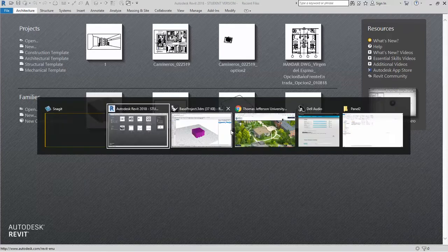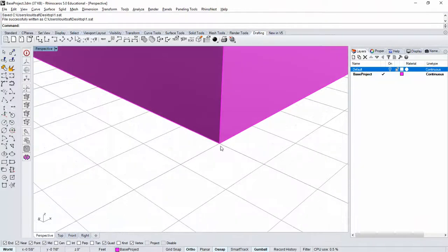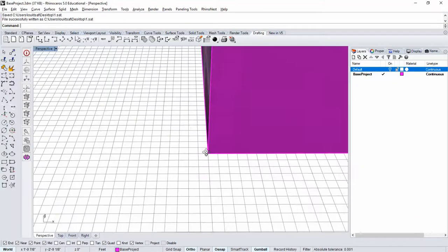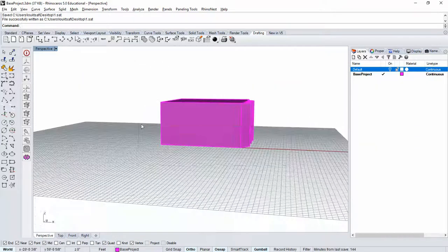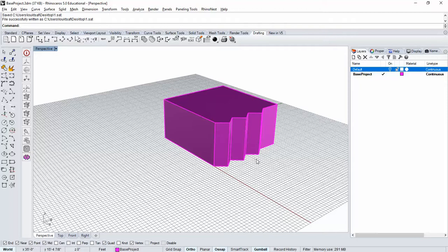I'm going to jump into Rhino, and this is your file. Make sure that it's actually on the 0 coordinate and that you don't have other elements such as the dimensions and the curves that made this project. Okay. What we're gonna do is the introduction or the first steps to develop this project in Revit, and then you will jump into another series of video tutorials that will explain more in detail how to incorporate the other projects that we have been doing in Rhino.